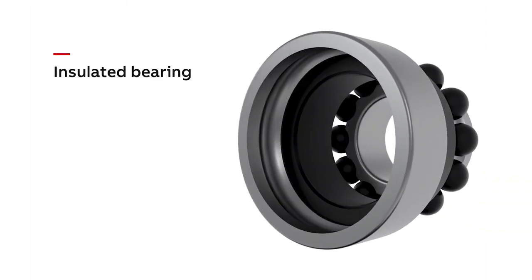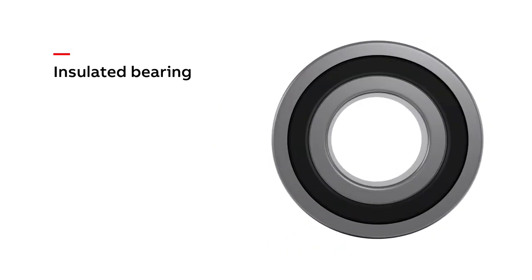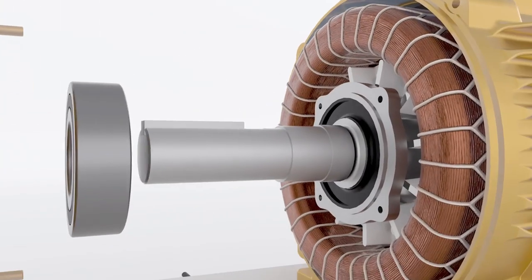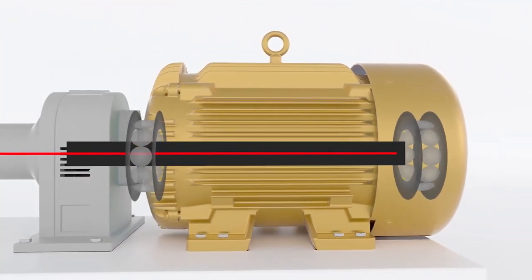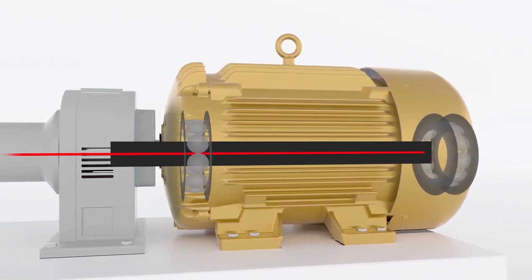Bearings made from an insulated, non-conducting material such as ceramic are another solution to eliminate the discharge of current through the bearings. Non-conductive ceramic materials prevent shaft currents from flowing through the bearings and damaging the motor. Since no electrical current flows through the motor bearings, there is no chance of current-induced wear.